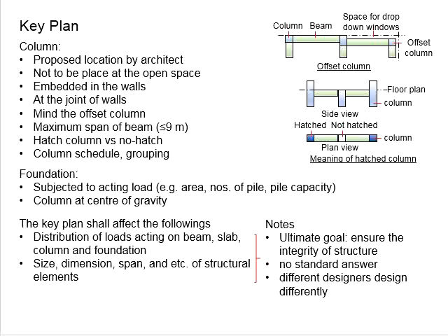This is going to be quite confusing, quite tedious to refer to, and every single column with a different design will be quite difficult to manage on the construction site. Normally we will reduce the types of columns within the structures. Let's say now you have the column schedules. Certain columns are grouped together.